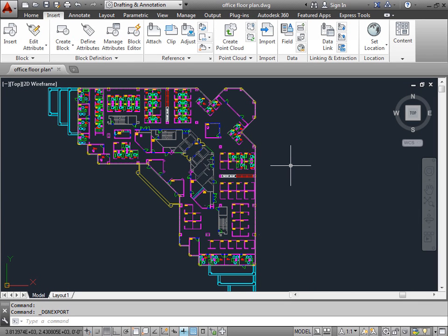Different versions. Tackling different file types is one thing, but sometimes you have to tackle a different version of AutoCAD, and that's a whole other thing. Somebody could be working with an older version of AutoCAD or an AutoCAD LT, and although they may be creating a .dwg file, the way those files are set up when they're saved may restrict older versions or newer versions from communicating with each other.